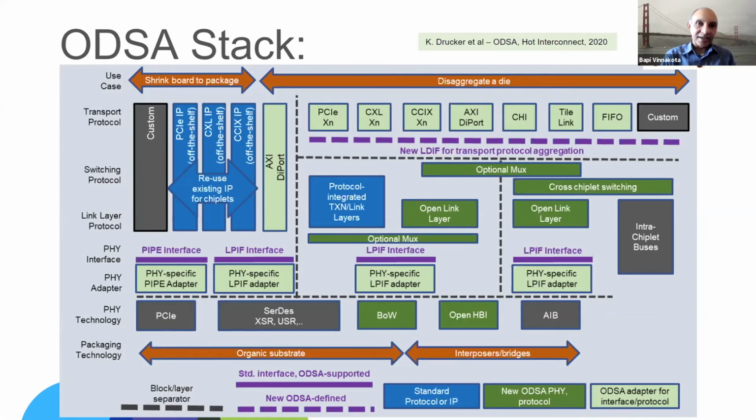And the way we do that is that we tell a die-to-die PHY to spoof being a PCIe PHY, to pretend to the PCIe controller, to interact with it the same way a PCIe PHY would in the data plane and in the control plane. And if you do that, now magically you can take a system design, replace the PCIe PHYs with die-to-die PHYs, and dramatically cut power dissipation.